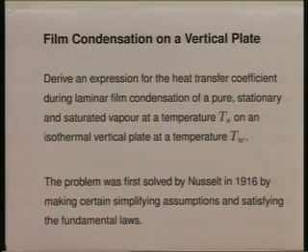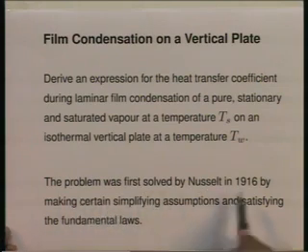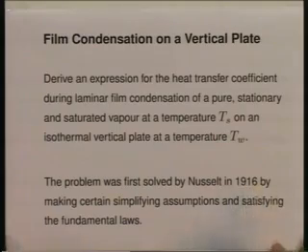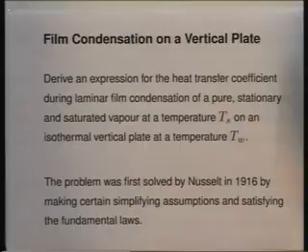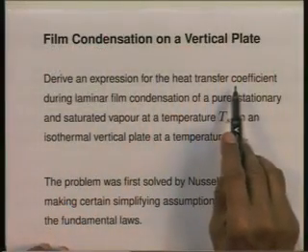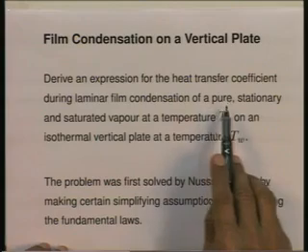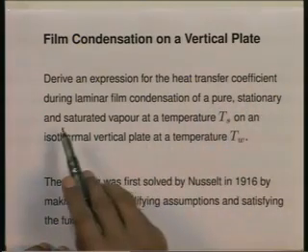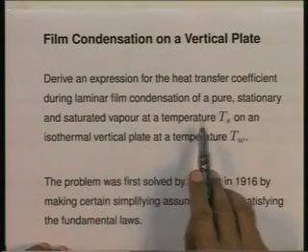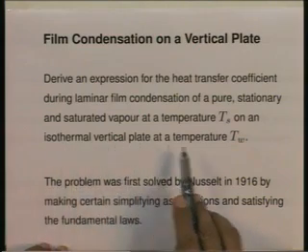And this is the classical problem, which was first solved by Nusselt in Germany in 1916. It is the classical problem of condensation, and we are going to derive the expression which was derived so many years ago. Let me again repeat that. Derive an expression for h, the heat transfer coefficient, during laminar film condensation of a pure stationary and saturated vapor at a temperature T_s, which is condensing on an isothermal vertical surface at a temperature T_w.